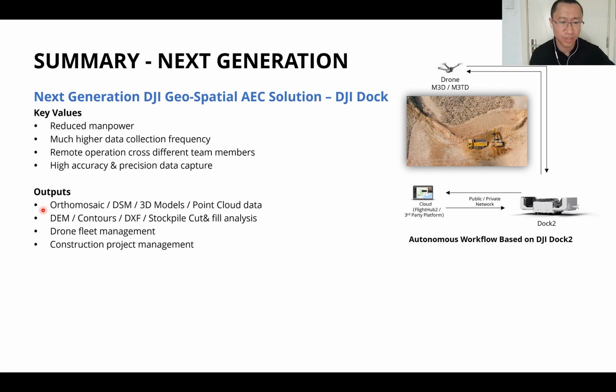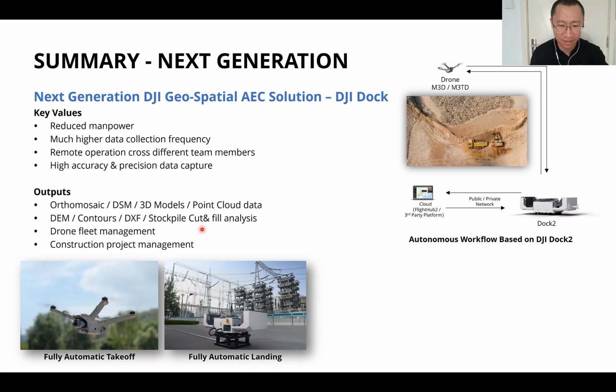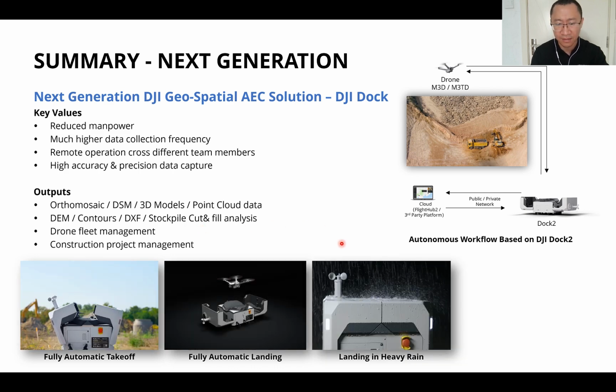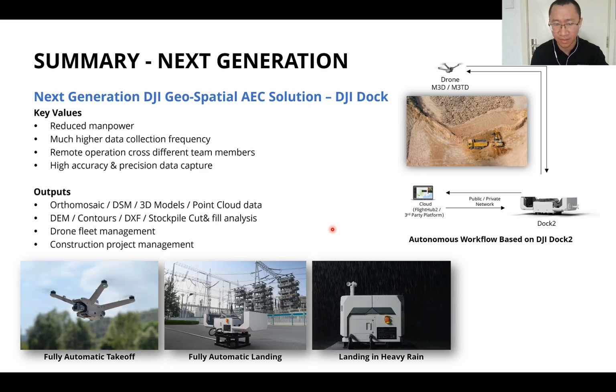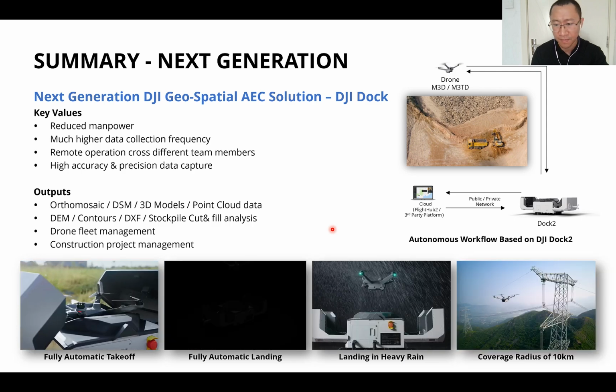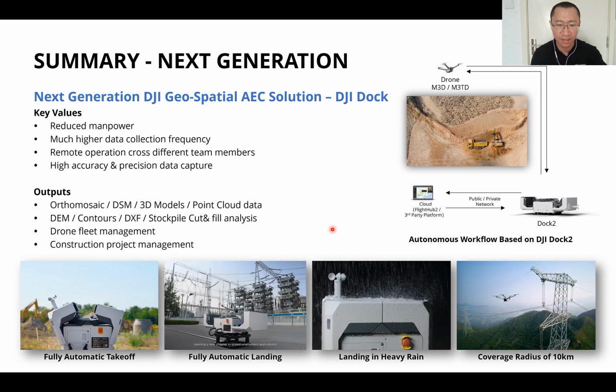So it can also generate lots of data and final results. For example, there will be mosaic, DSM, 3D model, point cloud, DEM, contour line, DXF, stockpile, cut and fill analysis, you name it. So the latest will be the dock tool, so it can automatically take off and automatically land, and even fly in a very complex environment, for example in heavy rain or with very heavy dust. And the single unit can cover a radius of 10 kilometers.